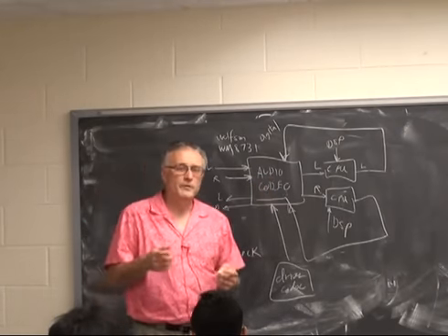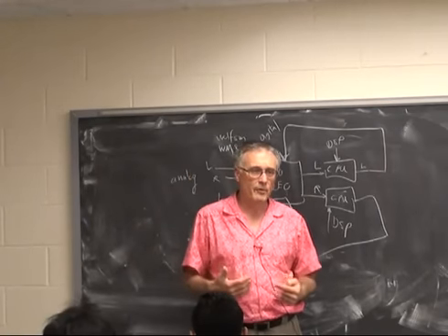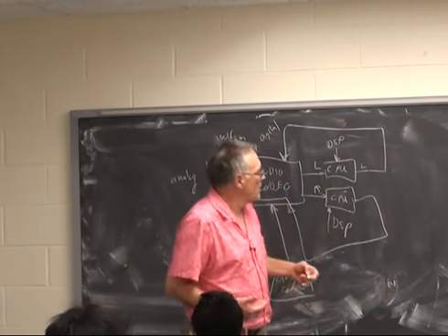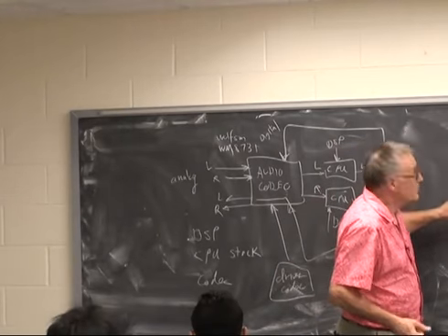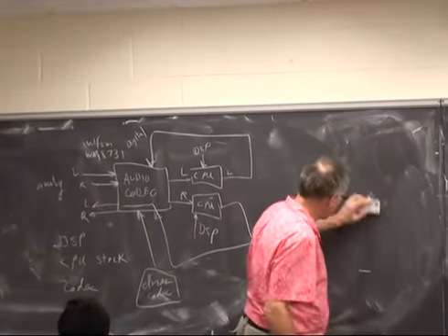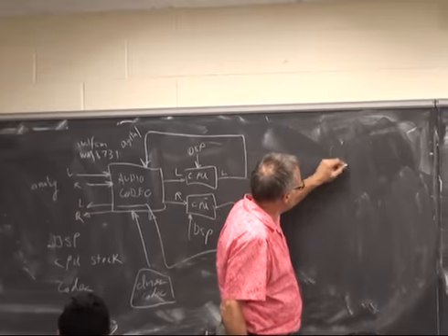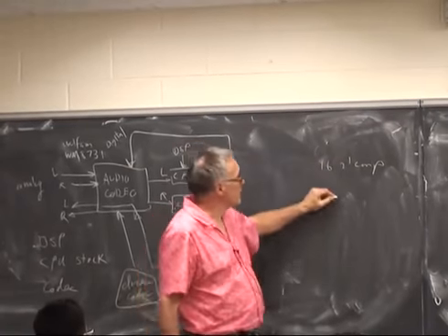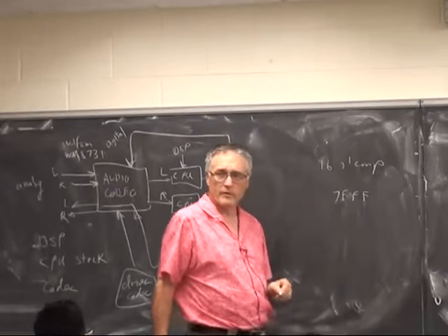And from your point of view, when you're writing this data, it looks like 16-bit fixed point 2's complement. So what would 2's complement 1 be, in 16-bit 2's complement? It's 7FFF, right?